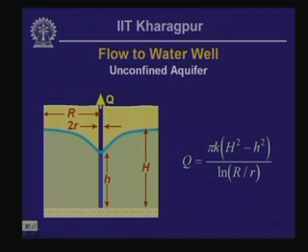Here also the water table after drawdown is represented by a thick cyan line as in the previous case, but here what you should notice is that near the top of the sequence of the geologic units you do not have the cross hatched layer. So the water table in this particular case represents an unconfined aquifer,